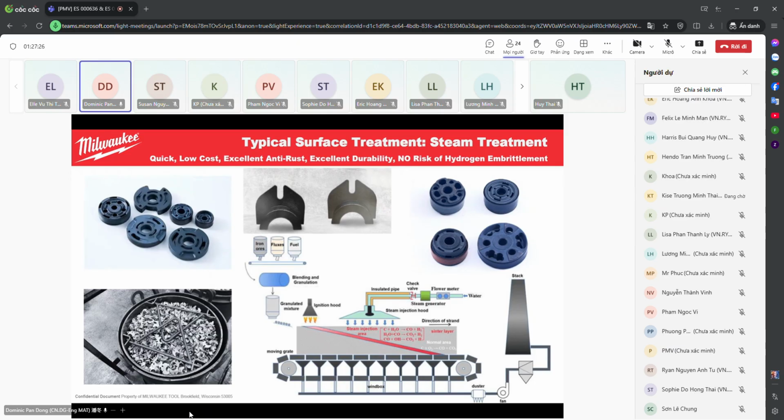That means the water steam, and the high-temperature steel reacts with the moisture, the vapor, and forms a beautiful black iron oxidation layer, and it can give us a minimum anti-rust performance. But again, pay attention, this is just a minimum. It can give us some safety for the parts' anti-rust during handling and transportation, but it cannot give you any warranty of the parts' anti-rust during service.